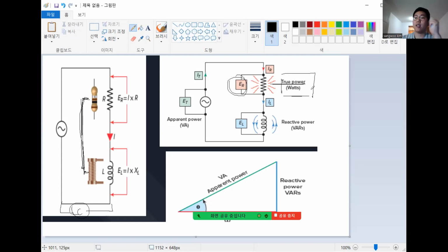I gave you money, it's gone. I used it or I lost it. By the way, the result is it's gotta be gone. So electrically, it's gotta be the heat loss. Loss is indicated by the heat. What we actually use is we say the impedance is R plus jX, reactance, right? So this part is actual loss, and this part I explained: I gave you, I stored it. I didn't use it, I give it back, right? So this is, we say, reactive power.